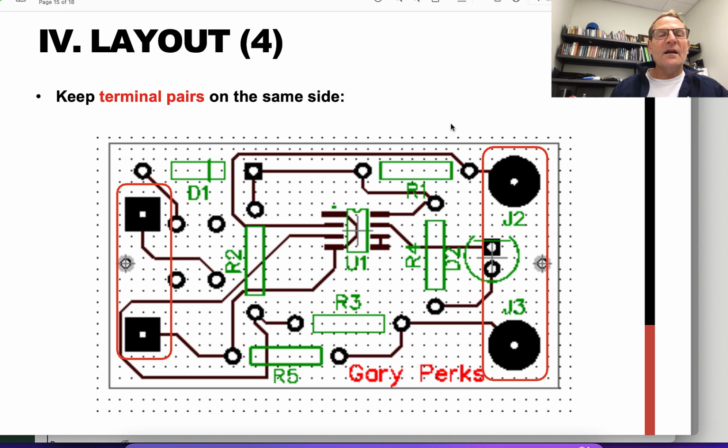So here we have an example of our layout. There are a few constraints. These are the large pads that are created for the connection of the 9-volt battery, which sits in a compartment off to the side in the device. Over here on the opposite end are 2 large pads for a large area of connection for strength to the board, and there will be 2 leads for the positive and negative probe leads for the device to be connected on the other end of the board for an efficient layout of things.